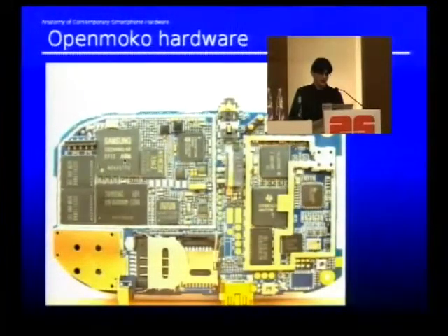We have the system on a chip here. This is the one which does not have the integrated flash and SDRAM. So we have the flash here, SDRAM here, and the S-Media here is the graphics accelerator. This one, the PCF50633, is the power management unit, which is the same that is used in the iPhone, by the way. We made NXP open the datasheet, so I'm sure people can have creative uses for that. That's the Wolfson codec for the audio side, and that one, I think, is the audio amplifier over there.